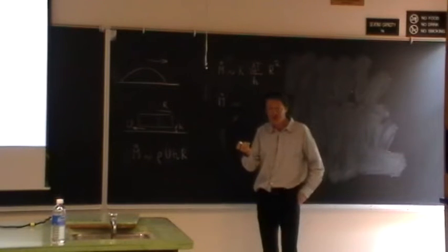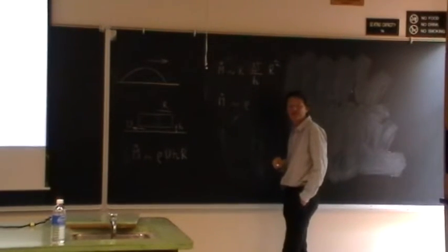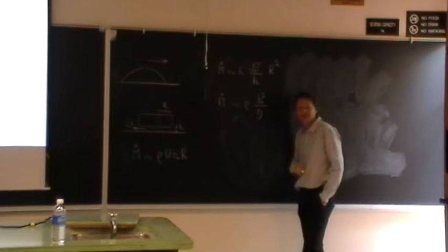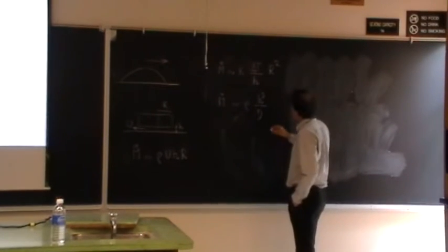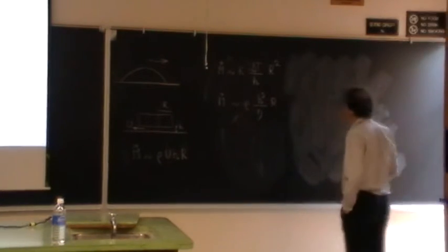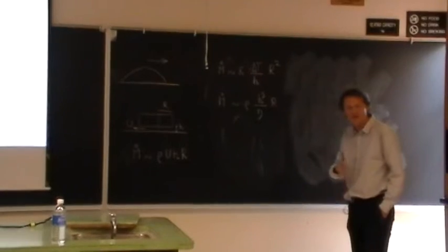And so you expect, because this is very thin, to describe this flow by the lubrication approximation. So the mass should be sensitive to the density of gas, to the cube of the thickness of the film, divided by the viscosity of air, or vapor, times the perimeter of your coil times the gradient of pressure, the driving force.